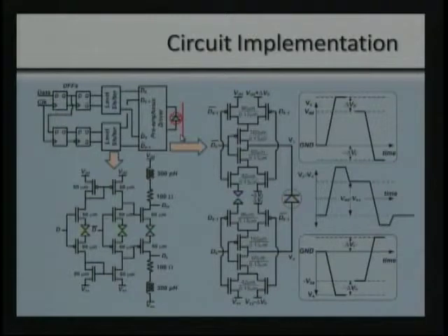This circuit implementation is a little bit different. As opposed to using a lot of digital processing to produce the duobinary signal, we can do preemphasis directly at the driver by modifying our inverters to be something like an AND. When we want to preemphasize the waveform to go from ground, for instance, to a rail higher than VDD, we produce a path that is gated by the current data and the previous data.